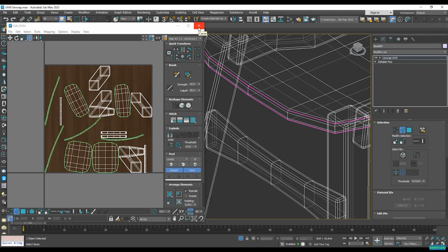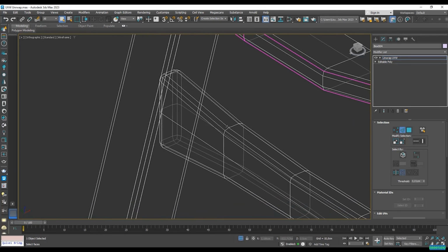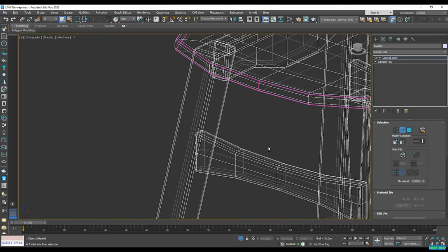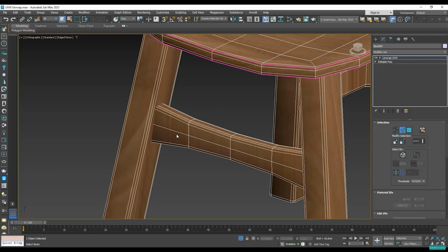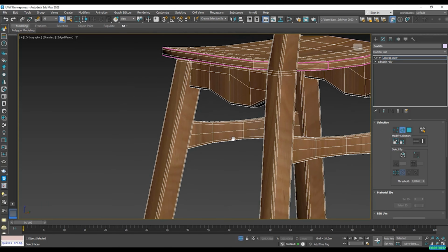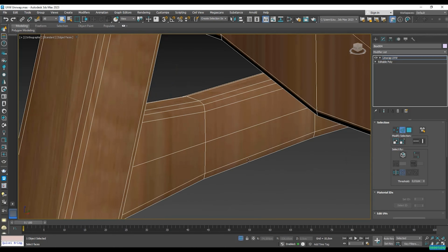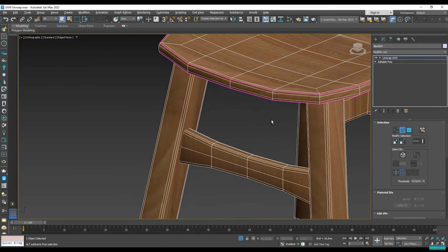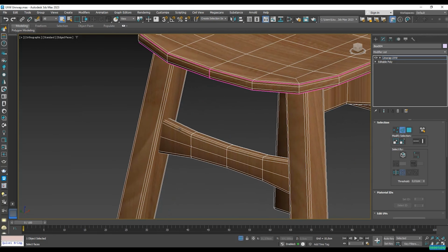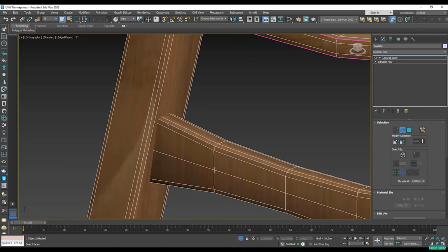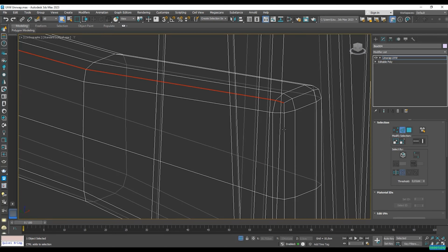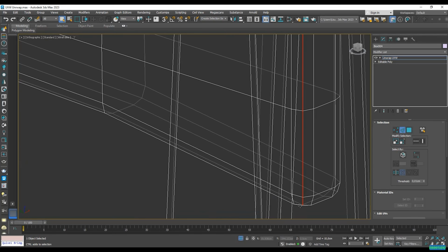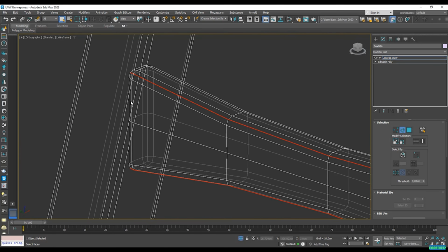So let's close our editor, and now let's select the edges. For this piece in here, I can actually cut it again into 3 pieces. So I'm going to have my front face, my back face, and then again the strip that is actually surrounding it. Now for this method, we have to press the Ctrl key to keep selecting our edges. So I'm going to just double click there while holding the Ctrl key, and I'm going to separate this surface from the rest.